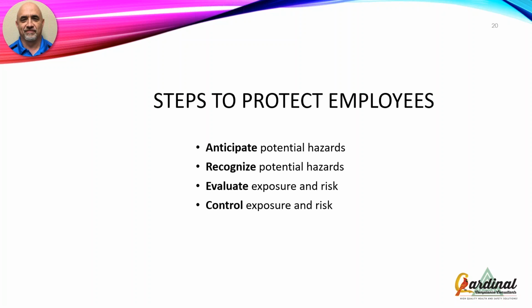In this case, I see a lot of times people say, yeah, I understand he's exposed to this stuff, but everything I've read says it's not a big deal and it's not going to cause any issue. He's right, metal fume fever doesn't cause any issue. But when we get into recognition and evaluation, what that's telling me is that you are definitely getting something into your system. So then we start driving down a step further. Lead, cadmium, manganese, antimony, zinc. Are you welding on galvanized steel? Hexavalent chromium? You start getting into all of that stuff, and this is where we start this industrial hygiene work.